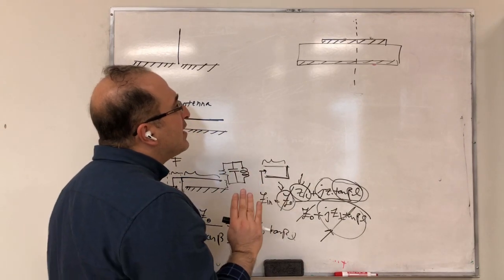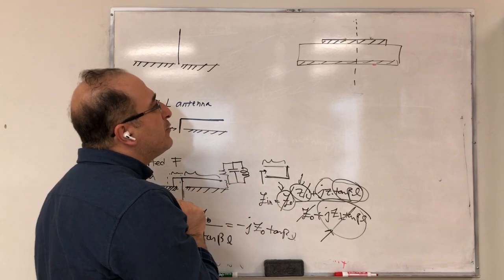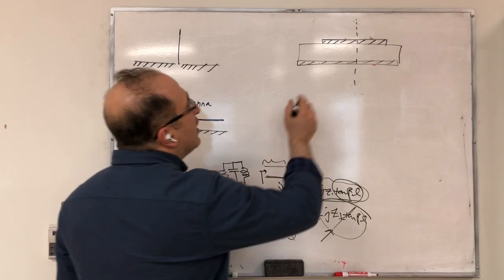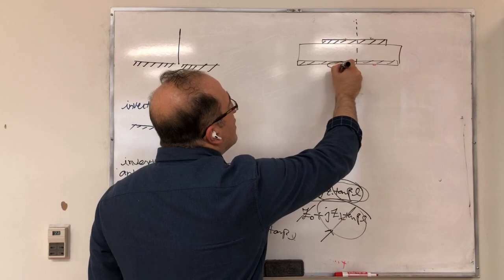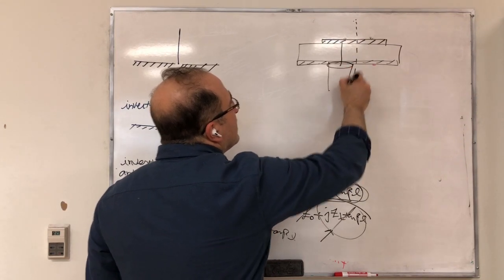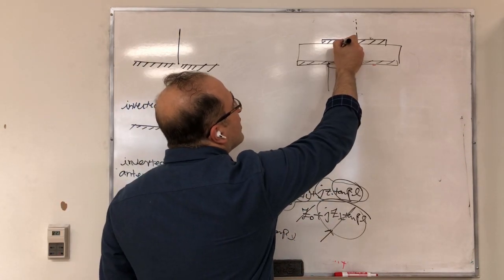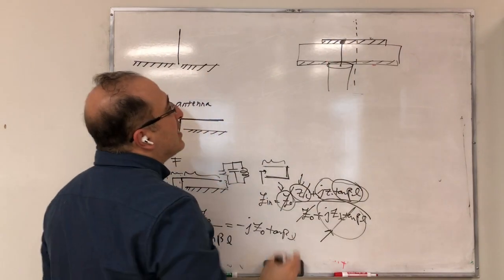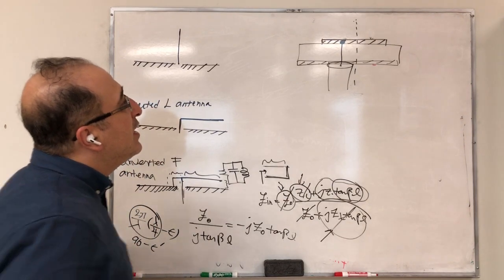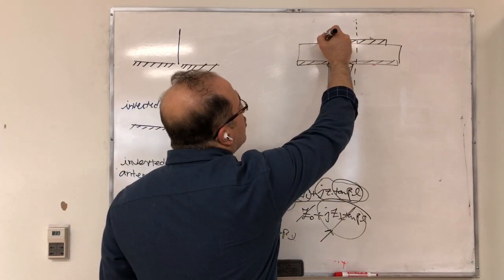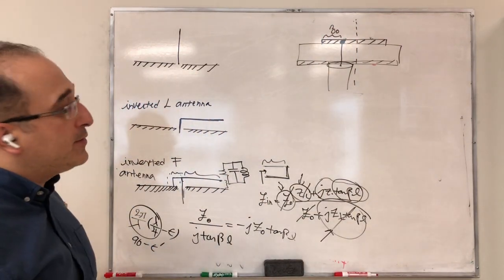But if I'm not mistaken, let me go by the style that I did for the teaching of the feeding of the patch antenna. So I think back then I had my probe here. So I said this is a probe fed. You bring a coaxial cable from the back. The inner conductor touches somewhere here. So if you feed from here, then you're going to have a large input impedance. It's difficult to match, so you do a little bit of offset. If I'm not mistaken, we called it Z0.